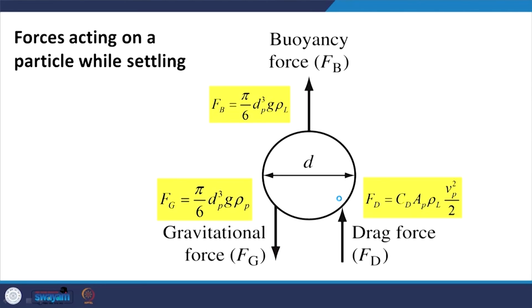And just a quick recap of where we were and how we came about that. In general, sedimentation, what are we talking about? We have a tank. What's the role of the tank? We are providing enough time for our particle which is flowing along with the water. So water is flowing in this way, I'm talking about horizontal flow. By the time the water moves out of my settling zone, the particle should have settled down.